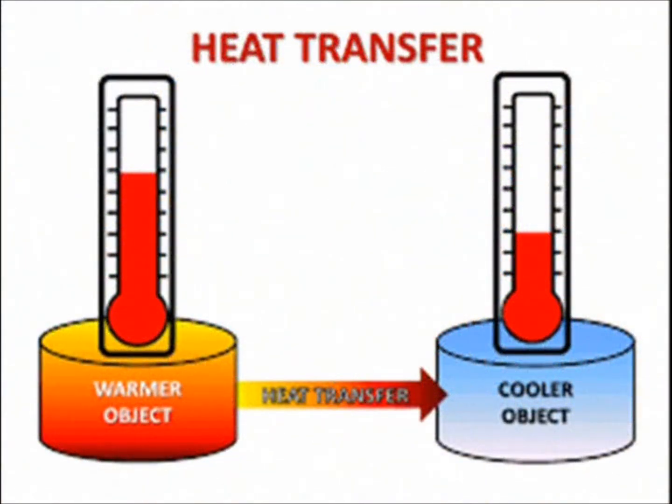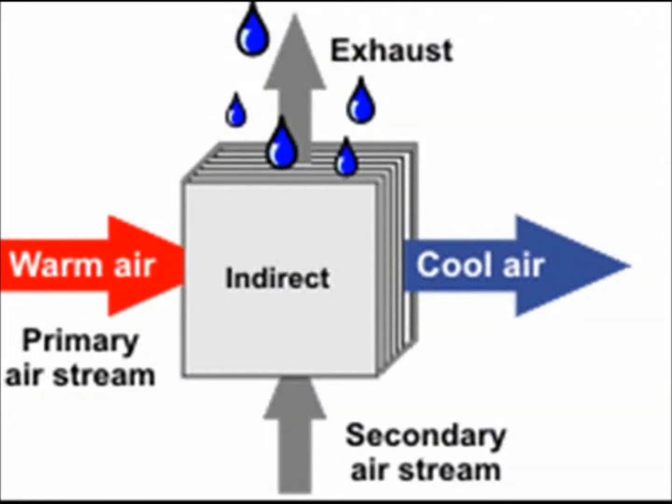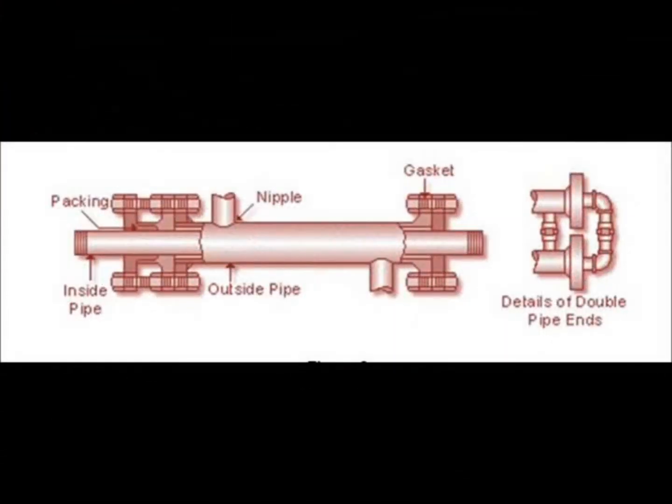Thermal exchange devices. As said earlier, there are various ways to transfer heat. Some of the methods are direct contact exchangers, in which the heat exchange is made by physical mixing of the fluids. Indirect contact exchangers are those in which fluids do not come in direct contact, do not mix, but are separated by a solid wall, a space, or even a time. Reciprocating heat exchangers: in them, both fluids run through the same space alternately, so that a surface receives heat from the hot fluid, to sequentially transmit it to the colder one when contacting the same surface.